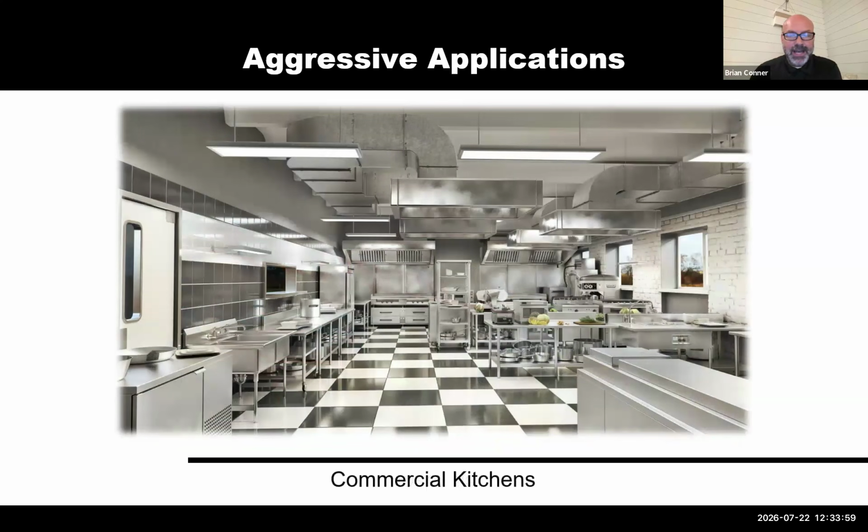And of course, inside of hospitals, you have commercial kitchens as well. Commercial kitchens can be potentially hazardous to any type of piping systems for any variety of reasons. Of course, in commercial kitchens, you've got lots of fats, oils, and greases that inevitably are going down the drain. You've got very high temperature discharges from sanitation equipment or from pasta pots or things like that.